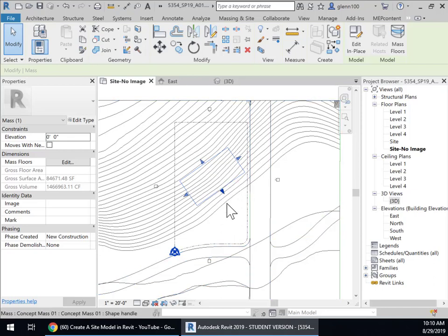So it's east of south, not true south. This is not true north. It's west of north, right? But let's say that I decide, well, that's the direction I want to be. In that case, if I'm modeling to this, that's going to make it much more difficult to go into more detail. What I'd like is for my project north to be actually parallel to that object.